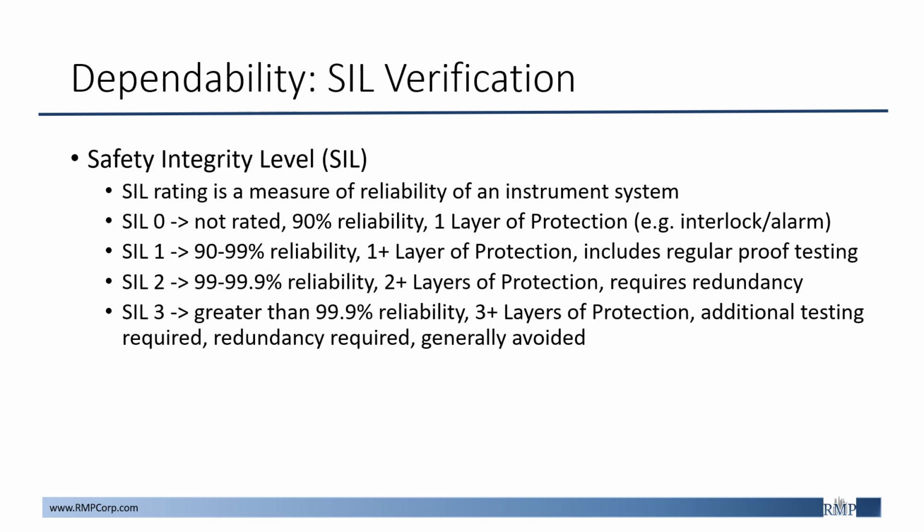SIL verification is one aspect of IPL development that is important for the overall risk reduction factor associated with an IPL. So the risk reduction factor is how your overall risk gets reduced based off of the reliability of your IPL. So for a greater SIL rating, measuring its reliability and giving you a greater RRF value, thus reducing the risk as your SIL rating goes up.